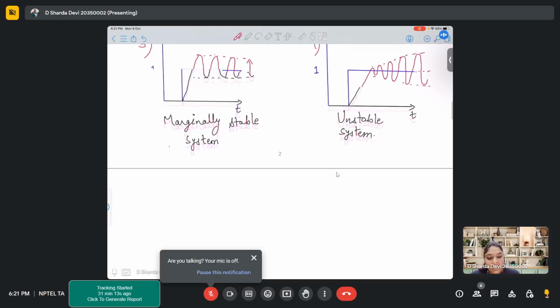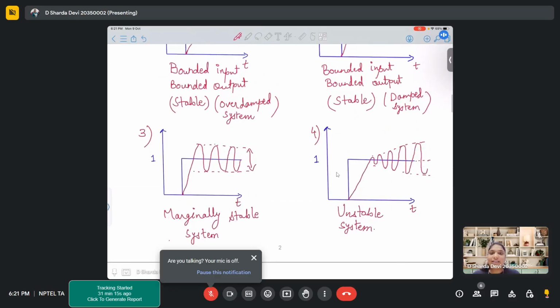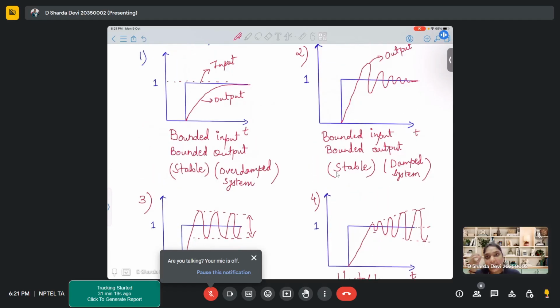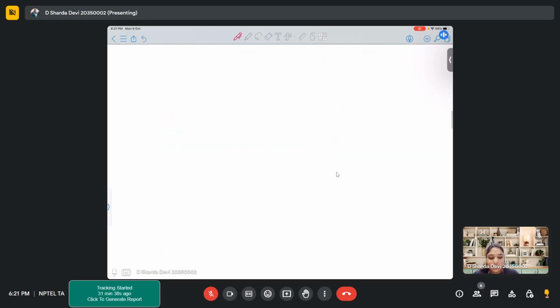Ultimately, when we say your circuit gives a certain behavior, what is the reason behind that behavior? It is the placement of poles and zeros, correct? How your poles and zeros are placed in a certain domain, majorly the frequency domain, will decide your circuit behavior. So the plane that we use to analyze this pole-zero behavior is known as the S plane.